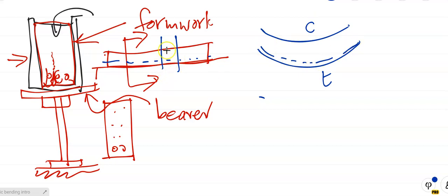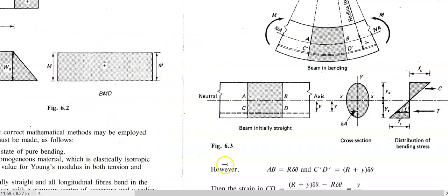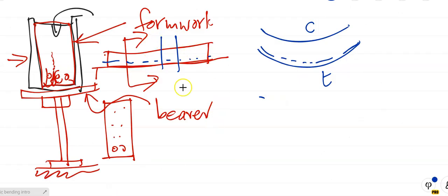So there's my steel there, and this sketch here is just a piece of that beam, which is that over there. So there's the top of the beam, there's the bottom of the beam, and there's the steel running through the beam in dashed line. So why is it the dashed line? Because it's hidden detail. We can't see it. It's inside the concrete over there.